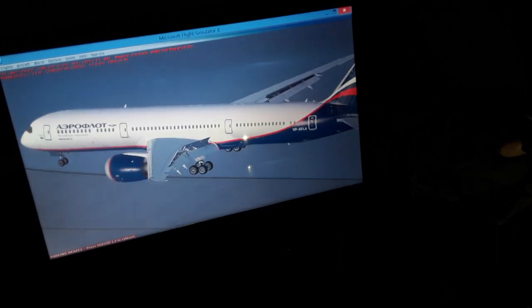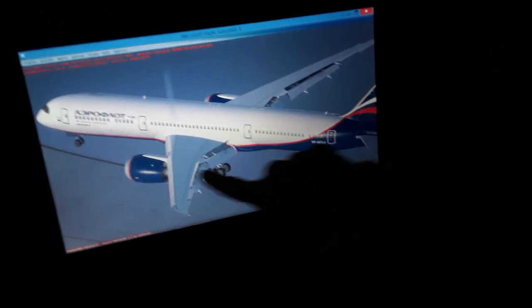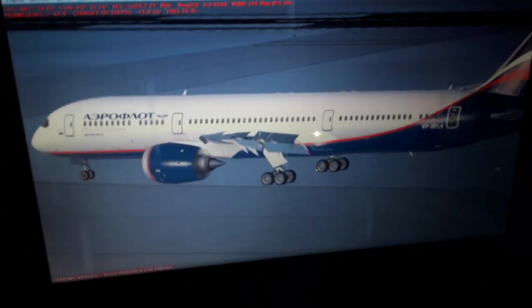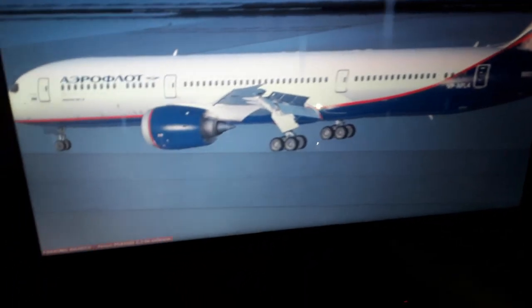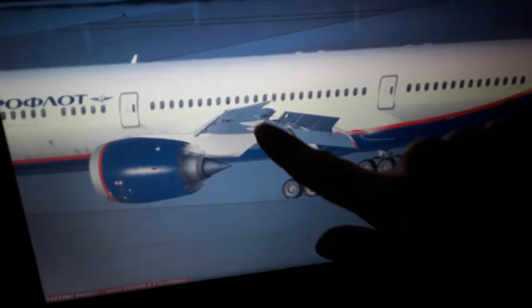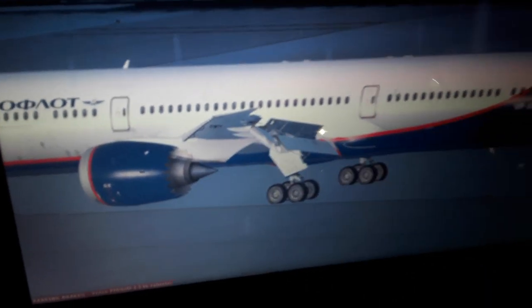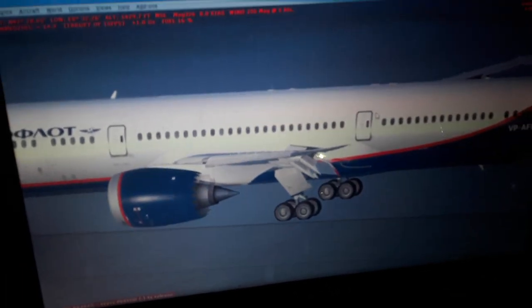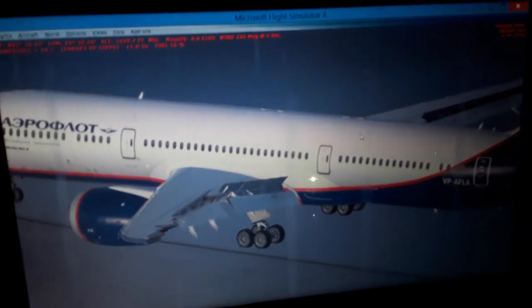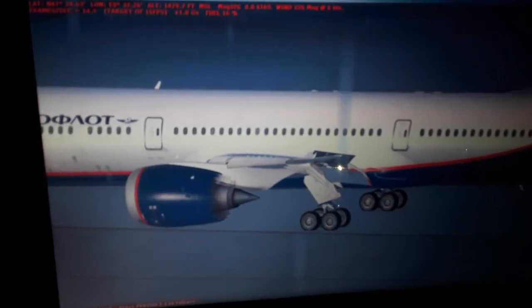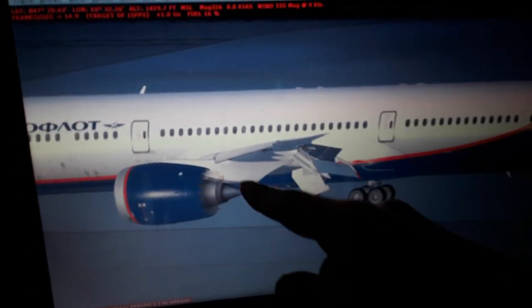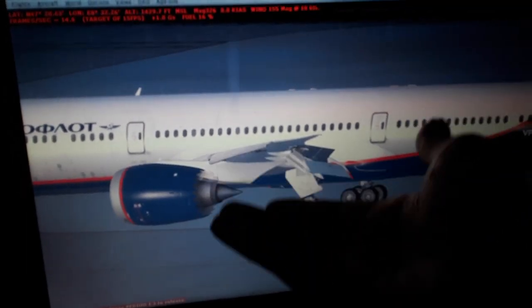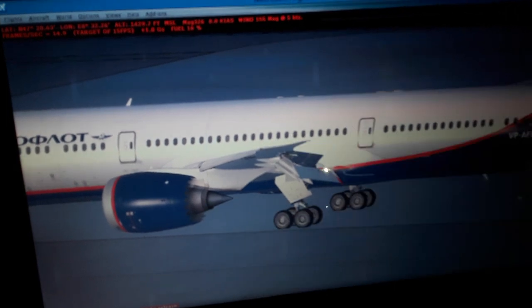Vertically we have also, as I told you, the thrust vectors from the engines that move forward, and when we fly you can see the surface of the wings. The bottom surface is more flat, and also we have the flaps extended down here. So also we have an angle of attack like this when we fly. So we have higher pressure below the wings when we fly because we have lower airspeed below the wings, using the Bernoulli theory of fluids, which pressurizes the aircraft wings and lifts the weight up into the air.